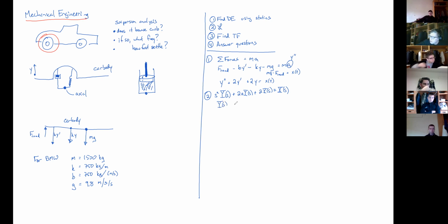And so now we're going to find out what that Laplace transform is. So we'll take our y of s, our output, and we'll just factor out our y of s. We get s squared plus 2s plus 2, and all that equals our x of s. So now, Sabine, tell me what our transfer function is, where we define our transfer function always as being our output divided by our input. So what is it for this particular vehicle?